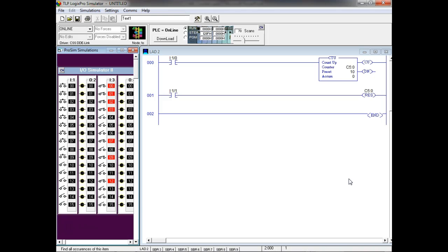Robots have encoders on them, and robots move pretty fast. I wouldn't do that with a software counter. So this is the big problem we have. In advanced PLCs, we'll show you how. You have instructions where you initialize it, and then how you access it when it's done. But everything we're looking at now is software.